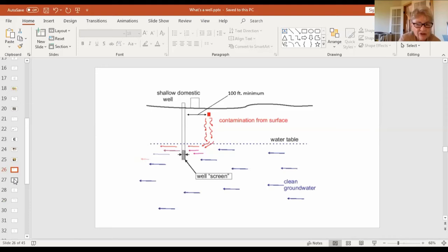I have a question. Sure. Are all contaminants basically near the surface, or don't some sink? Yeah, good point. They're called DNAPLs, dense non-aqueous phase liquids, and they are the bane of water contaminants. There are certain industrial solvents that do that. They're called sinkers, and they're hugely problematic.